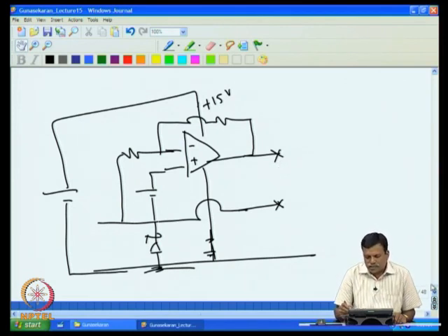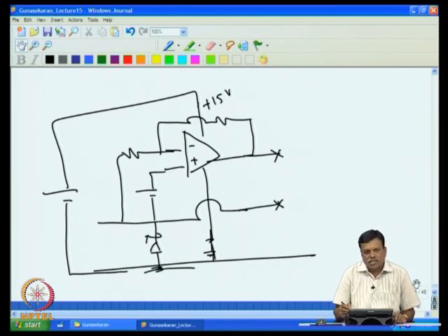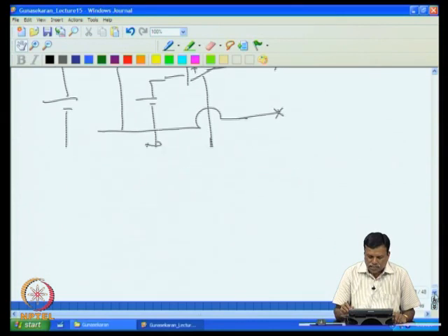So we had seen in the last 2 classes how to make a current transmitter to transmit the signal for a long distance. Current transmitters are used extensively in industry to transmit signals. As I said initially, this is to avoid noise pickup, because a magnetic field in the loop will induce a voltage, but as long as the frequency response of the current transmitter is good, they will not respond to the magnetic field. So that's why current transmitters are used.